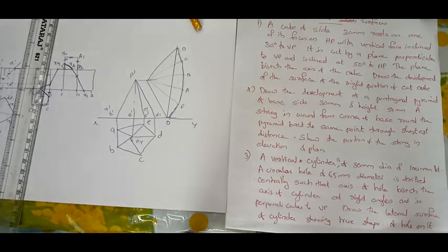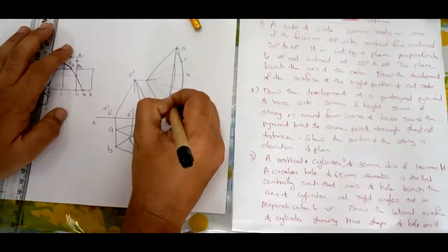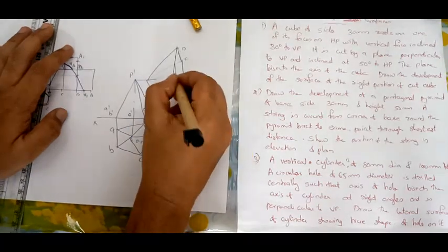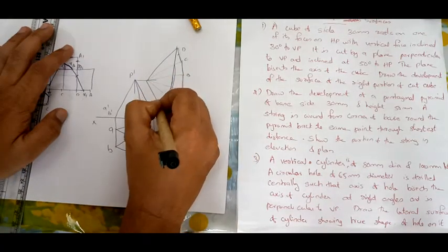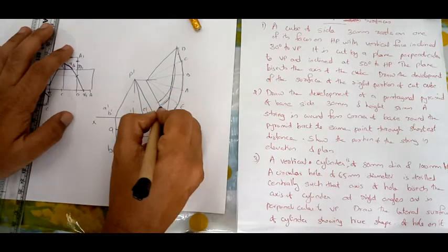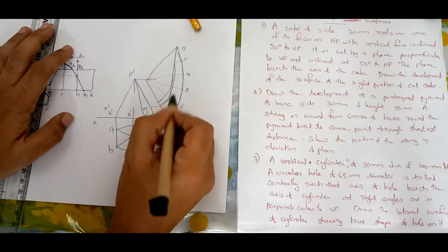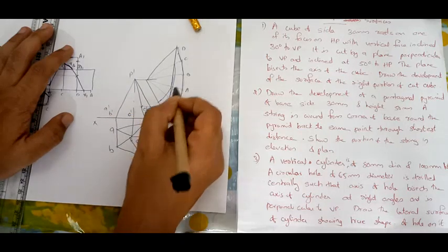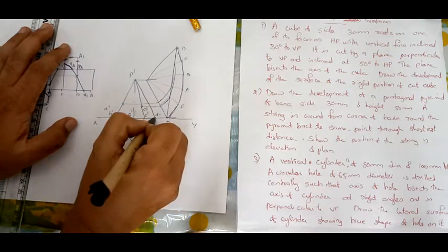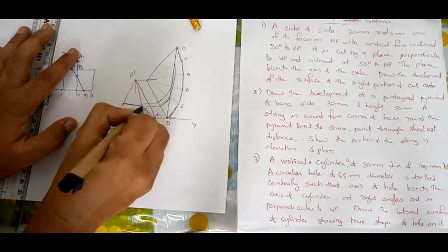It's very simple. See, you have to rotate. D is here. So C, and if you rotate, C and E will be passing through the same point. C and E should pass through the same point. Similarly, B and A should pass through the same point. We'll be getting like this. 3 points are there. D is here, E and B here. So D you will get like this. If you are projecting from here, this is actually E and C, right? So projecting here, you will be getting it; here it is A and B, right? So projecting it, you will be getting like this. So here it's not a curve, it's a straight line. So this will be the straight line you'll be getting.